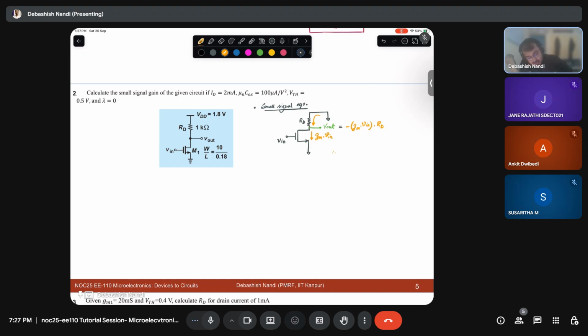So my Vout by Vin, or the small signal gain, becomes GM times RD.